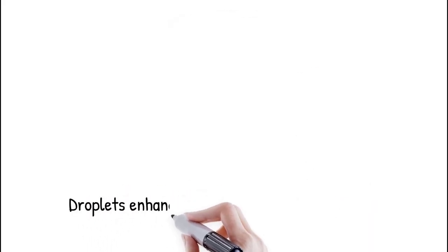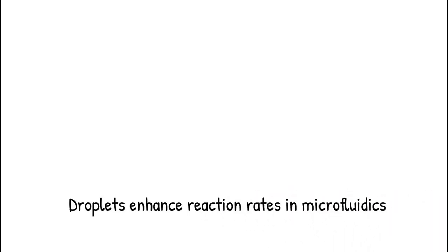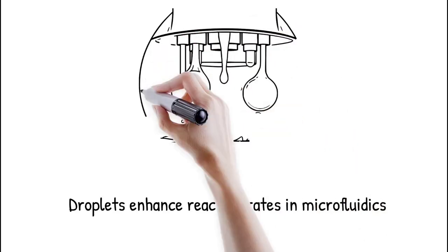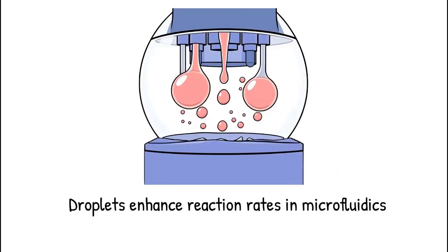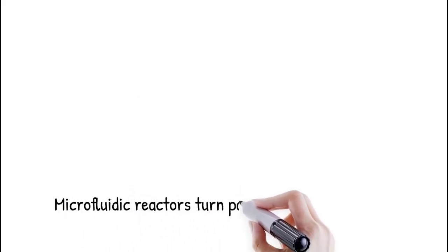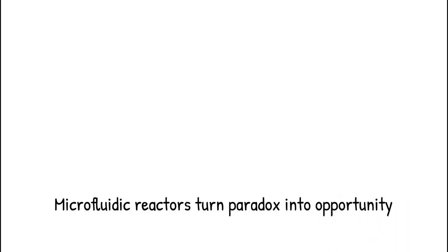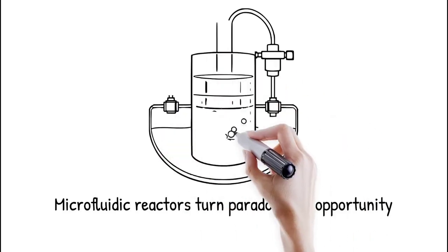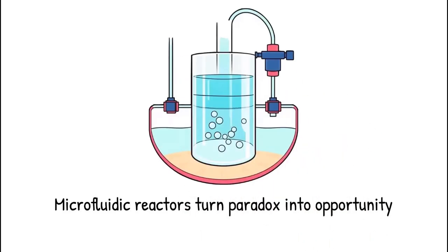Vigorous mixing at low Re overturns assumptions in microfluidic design. Engineers once expected diffusion-limited transport to dominate. Instead, droplets display active internal flows that enhance reaction rates. This enables faster biochemical assays, nanoparticle synthesis, and crystallization control. Microfluidic reactors rely on these effects for efficiency.